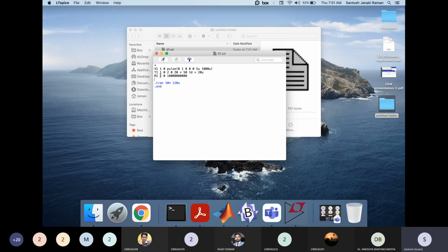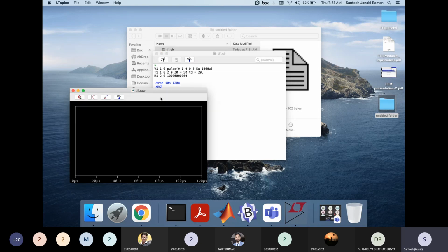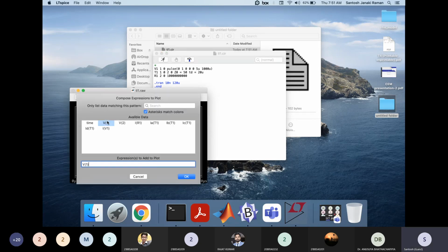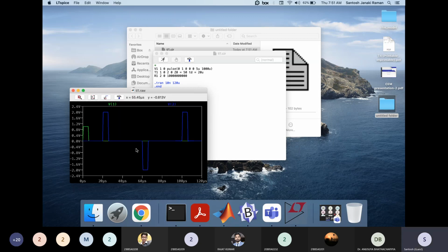That is, when you have a load that is larger than the surge impedance, right? In such case, the voltage always increases at the load side. Let's say you have the voltage at V1 and V2. So the V2 will always be greater than V1 if the load impedance is greater than the source impedance. So this is what happens.